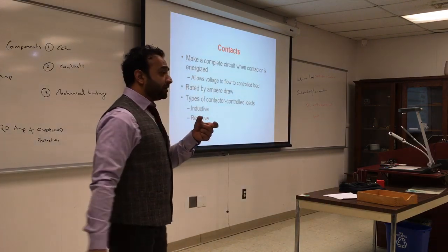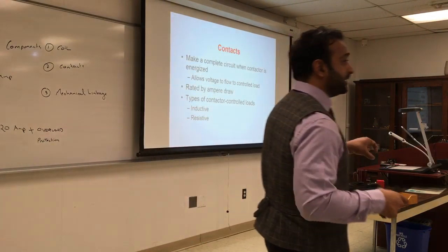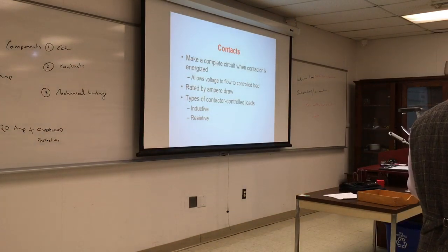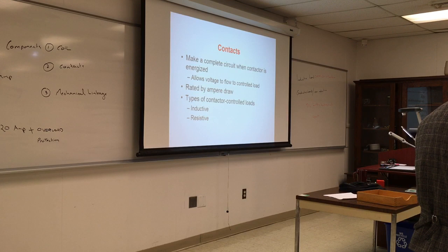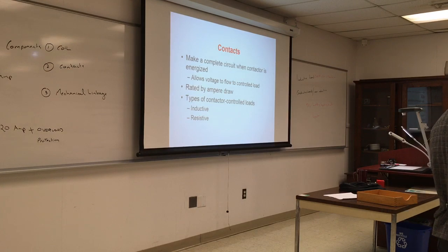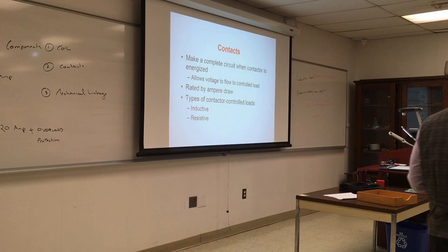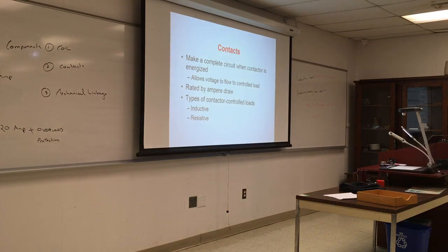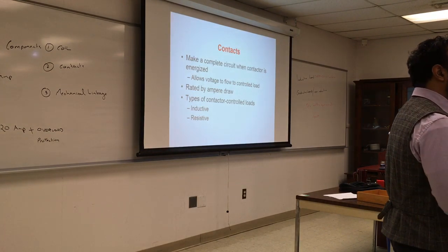Contacts, they are the parts that are connecting the circuit together. So you can understand how it should be like very solid contact. If it's touching part way, it's not going to give you good contact. So you want something to snap in and stay. And that's why a lot of thermostats with the spiral, they have a magnet, just a permanent magnet, just to make the sticking snap action very strong. Not these ones, the old ones with the spring. So you want solid contact, you don't want it to be halfway.